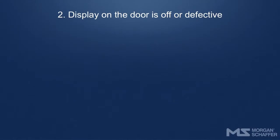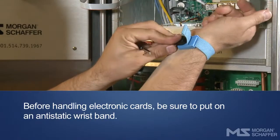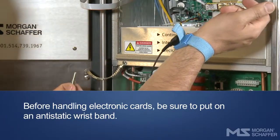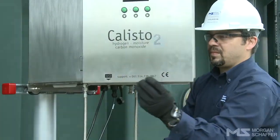Display on the door is off or defective. If the Calisto's display is off or incoherent, there is a problem related to the display or the power source. Before opening the Calisto, be sure to put on an anti-static wristband. Open the Calisto's door.